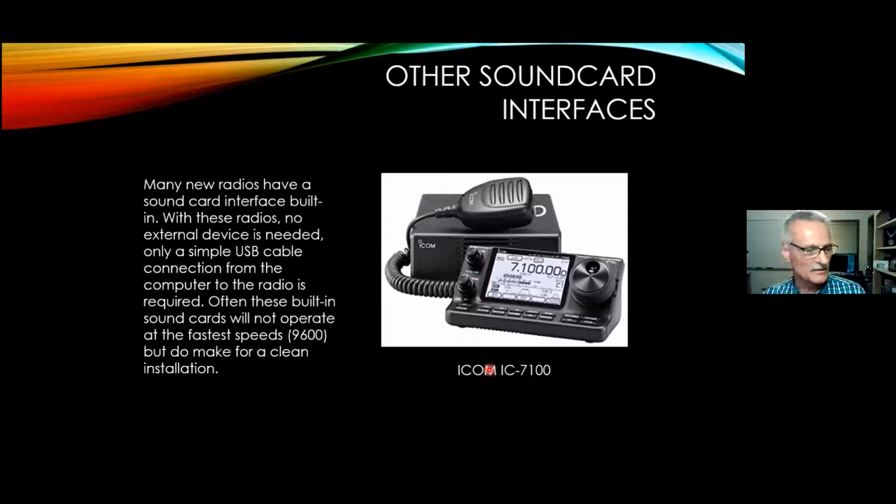Don't forget that there are many transceivers nowadays that have a Soundcard interface built into the transceiver. I've had folks ask questions saying I'm having trouble getting my SIGNALINK to work with my IC7100, and I scratched my head for a minute and said, why are you using a SIGNALINK? They said, well, I want to do digital. And I said, it's already got a Soundcard interface in it. All you got to do is plug that USB cable in and you're good to go. And they're like, oh, why did I spend the money on a SIGNALINK? So keep that in mind.